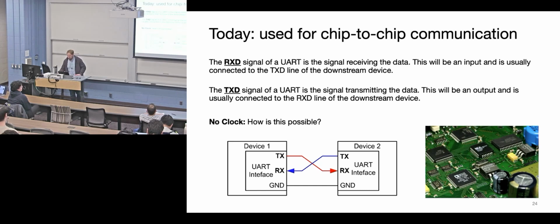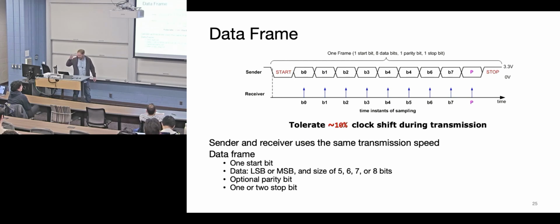Is the number of bits that can be transmitted at a time already determined for a device? Yes. It's 5, 6, 7, or 8 bits, plus a parity bit, plus 2 stop bits. So at most, you're going to get about 10 bits out. Can a device give up to any of those sizes? Well, the receiver has to know what to expect. Most devices can change the amount they put out, since those are configurable things, but at runtime both devices have to know what to expect.